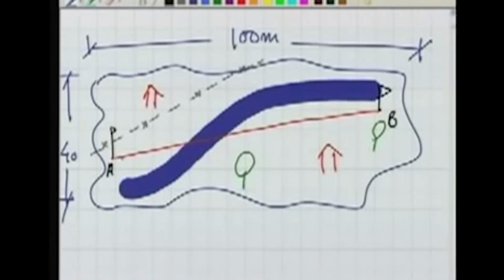Okay, I walk along this line, let us say a length of 10 meter. Then over here is one telephone pole, and from this telephone pole I drop a perpendicular on my length, and this perpendicular length is 5 meter. I take this measurement because I am walking along the chain. The chain is spread here, for example. So I know this length, which is 10 meter. I have dropped a perpendicular from the telephone pole on this chain, and it measures 5 meter.